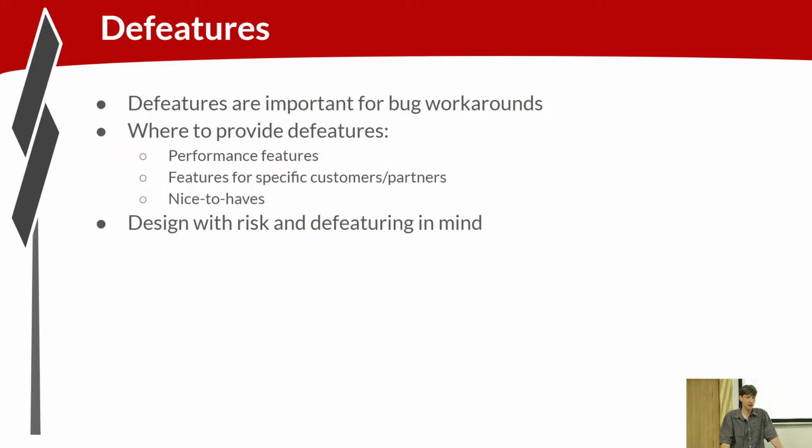Often they're features that are not mainstream important for all customers. In particular, they might be performance features. A performance feature you can turn off and still function correctly; you just take a performance hit. So things like that you want to provide D-features on. When you're designing your logic, like we designed the register file bypass, maybe we want a D-feature.